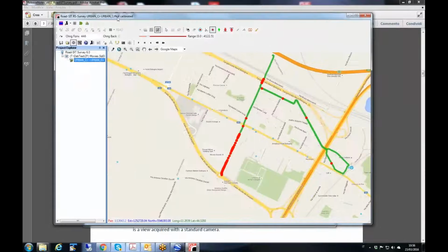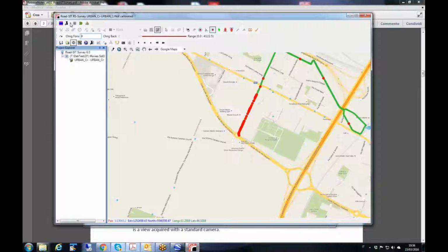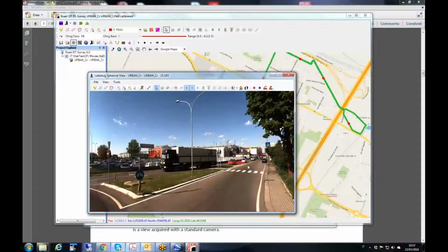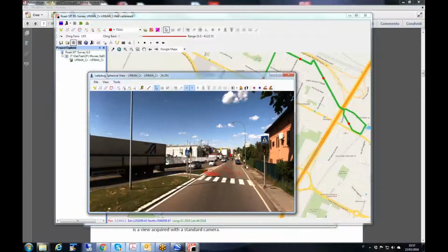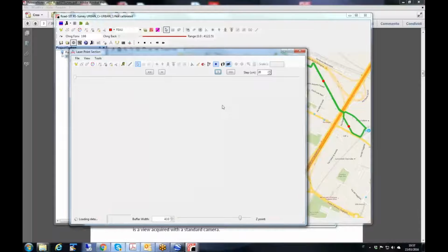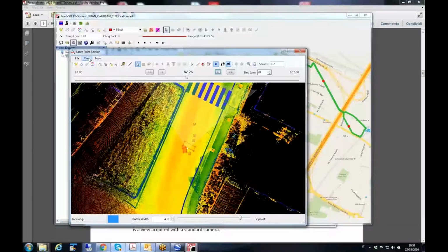Okay, you see in blue there is a technical drawing of Bologna. This can be very useful if you need to survey and make topographical drawings. You can upload here your drawing and follow the drawing directly on the map. To do this, it's very simple. You must go here in Map, add a vector layer, so add a DXF or shape file, for example. You have this one here.